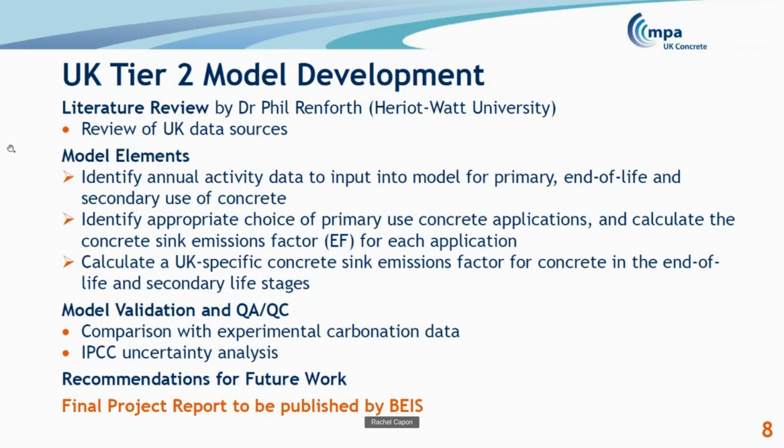So, to develop the model, we've reviewed UK data sources. We need to identify annual activity data to input into the model. We need to identify appropriate concrete applications and calculate a sink emissions factor for each application. We also need to calculate a sink emissions factor for concrete at the end of life and in secondary life. So the focus of the model is really on identifying the activity data and calculating emissions factors.